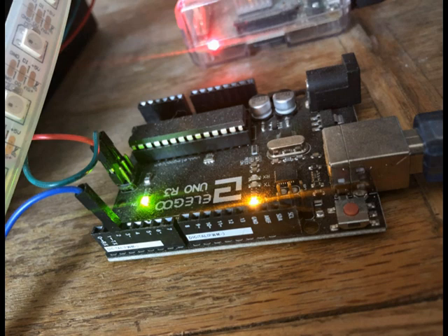So you will need either an AllPixel device or an Arduino of some sort. The AllPixel is very much plug and play. The Arduino requires some configuration, uploading a sketch, that sort of thing. I'm assuming that you're somewhat familiar with those actions, so I won't go through them here. But as you can see from the picture, the default sketch has the digital 2 line set for the data line that we will use for the pixels.